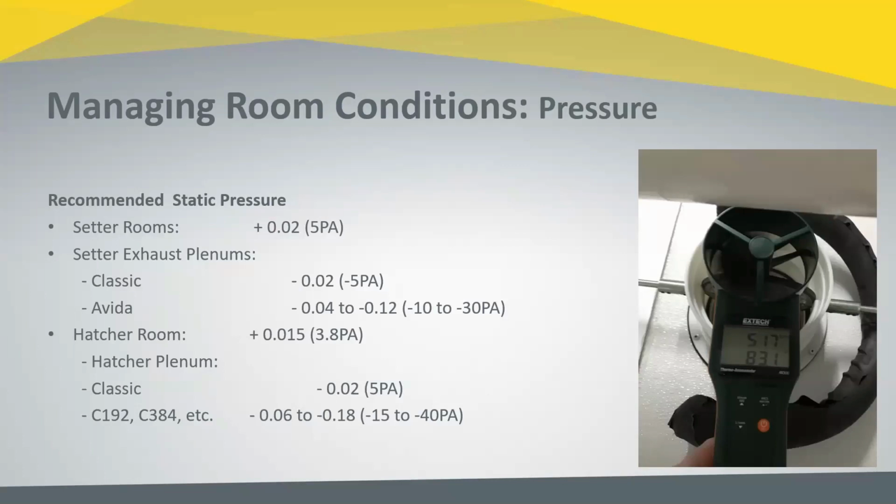Because yes, if you get too negative on a small machine and you have too much airflow, then the machine has to respond to that. That air from the room will generally overcool the machine. It may overdry the machine, and therefore now the machine is too low in humidity, and it may be having to heat at periods of time to overcome the increased air volume. So the key to it is measuring airflow.